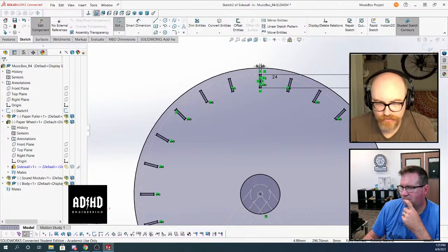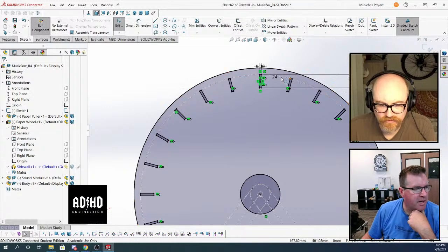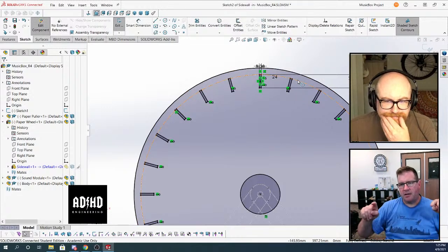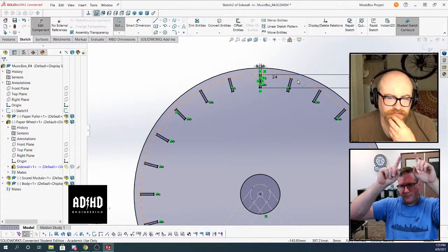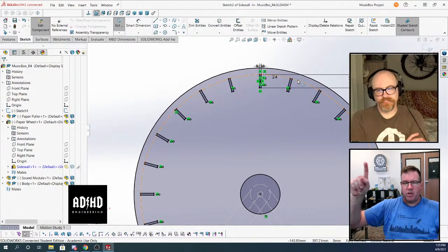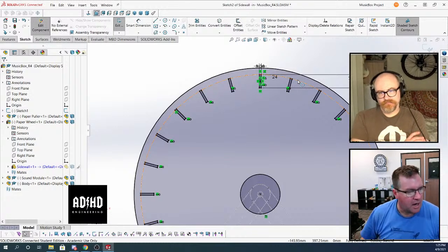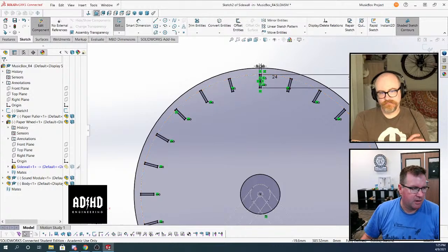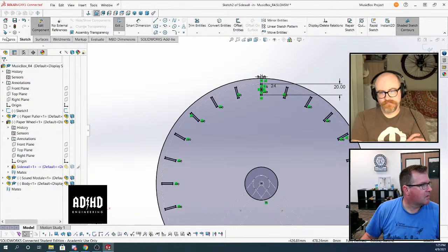What did you do to do that? I wasn't watching just now. So I just constrained them to this construction line, which I already had. Three points define a line. The first iteration of the pattern is there, and I just grabbed two others and constrained them to the line. I tried dragging it out, doing exactly what you said, and trying to recenter it, but I was having a hard time grabbing the center. So I just did it that way.